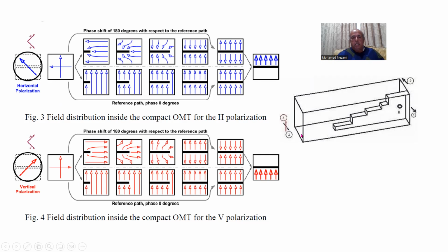If you trace the signal from here going in and how it behaves while the wavefront collides with this septum, you can trace out what happens. So we start out with a very tiny height in here, all the way to where we have full height metal that separates the two polarizations.